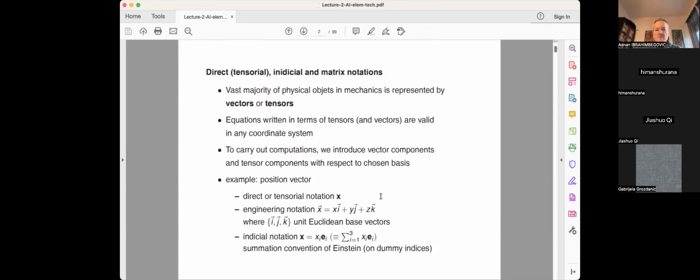In particular, displacement is a vector field, because if you take a coordinate system x, y, z, it has a displacement along x, along y, and along z. So you can characterize such a displacement as a displacement vector with components along the axes x, y, and z. Now, strain is a derivative of the displacement, the symmetric part of the displacement gradient, and the stress is a linear combination of the strain multiplied by the elasticity tensor. We'll get back to that in a second.